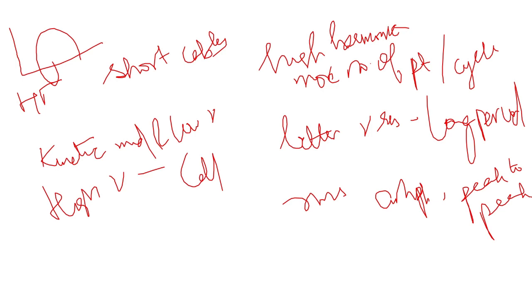Okay. So non-linearity, how do you check? We will apply different voltages and see the plot. If after a particular perturbation the plot becomes totally different, we say that non-linear effects are coming into play. So stability, how do we check? We will do one measurement, and after some time, immediately we will do another one. If for the same condition we get the same plot, we say that the system is stable.